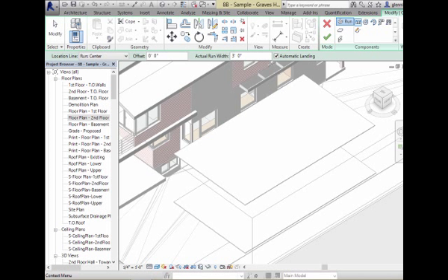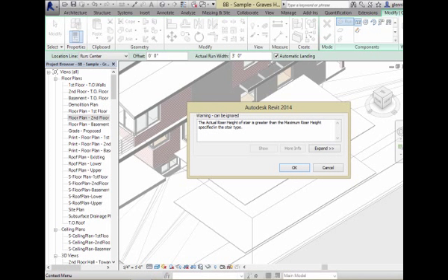It's dividing that. I can always increase the number of risers. That's okay. It just makes shorter stairs. It doesn't like us to decrease the number of risers, because if you decrease the number of risers, you'll probably start violating the rule about what the maximum height is. So 15 would be fine. If I try to take that down to 12, for example, it'll complain, whoops, the problem with this is this would give us 9-inch risers, and you told me that's not allowable. So it's just having us back off a little.